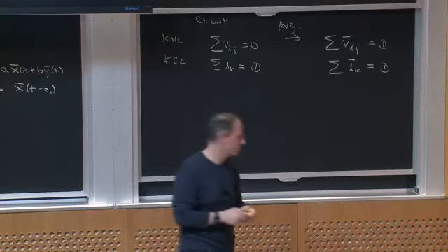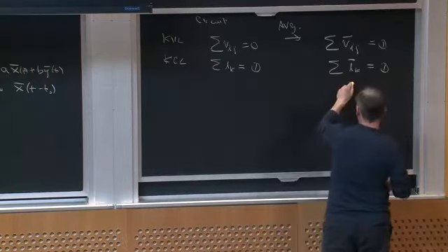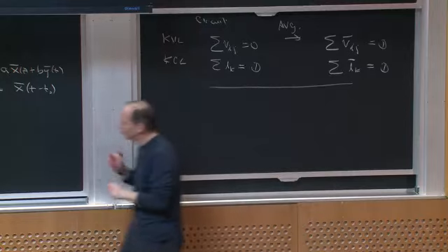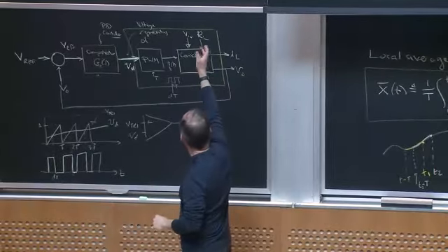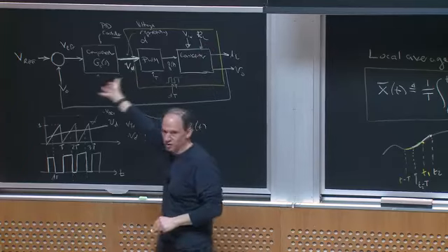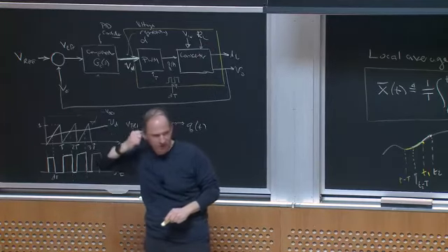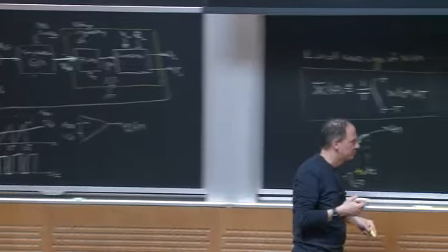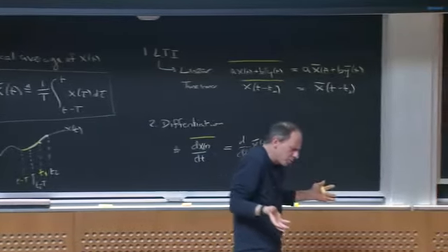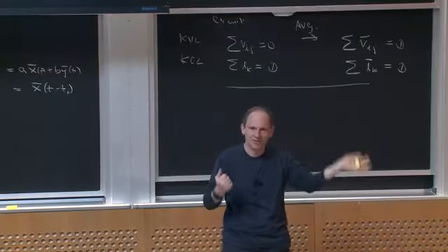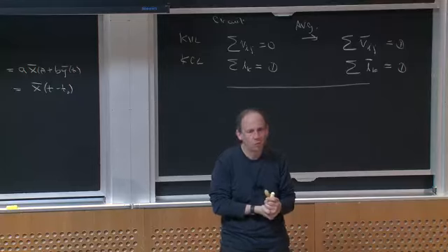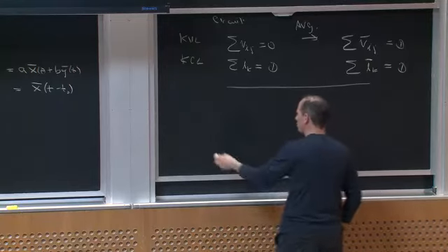Okay, let's start talking about circuit elements. What do I have in this circuit? If I come back and look at my boost converter, I have inductors, capacitors, resistors, and then switches and sources, right? Well, the local average of a source is just the local average of a source, right? So Vn would become Vn bar. But what about a resistor? What about my load resistor?